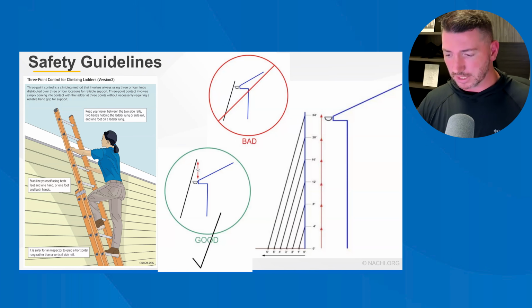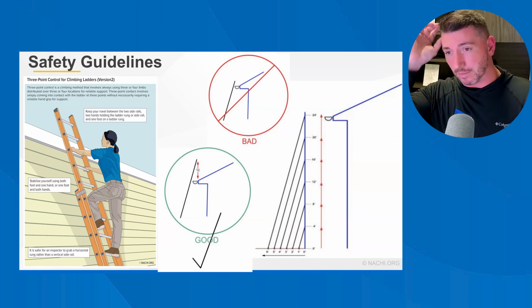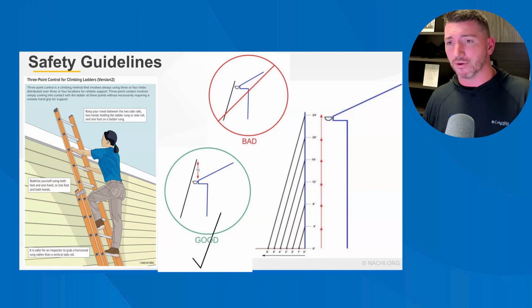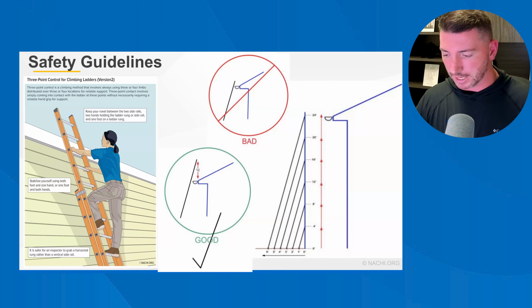Whenever possible, it's best to use 2 people to carry and set up a ladder, depending on what ladder you use. A 40-foot ladder is something I'm able to use, because of technique and strength and things like that, and I've been doing it for a long time, but some of those longer 32, 36, 40-foot ladders can be a bit cumbersome. So it's good to have a second person to help you there to set it up. It may not be practical, but it is best practice.